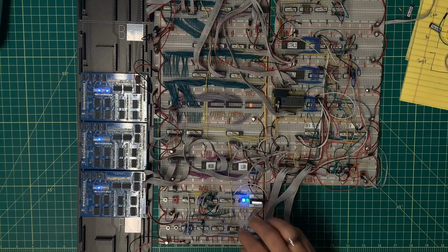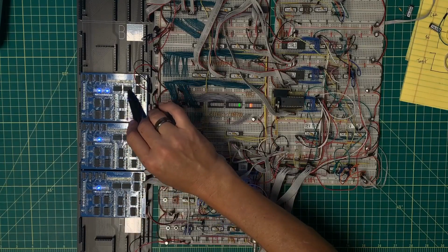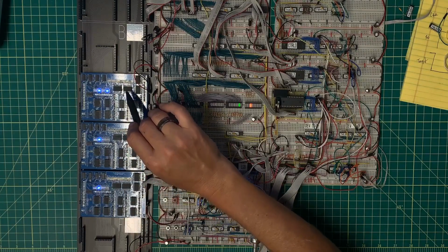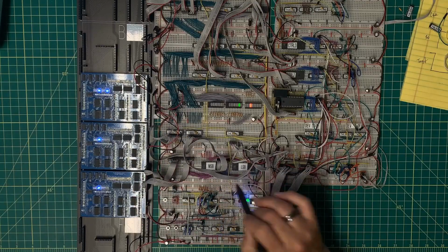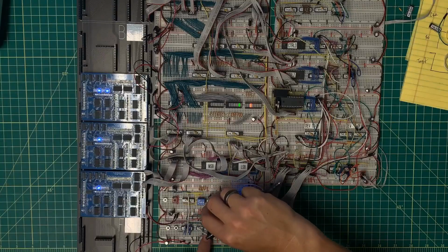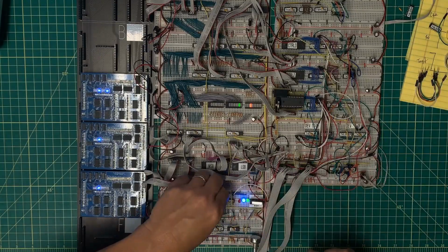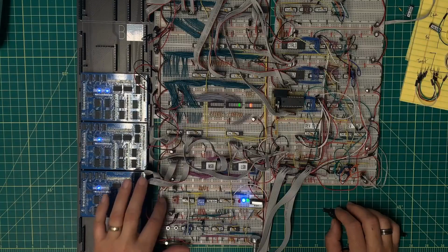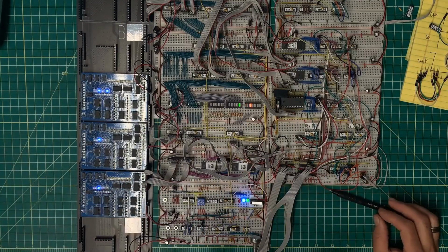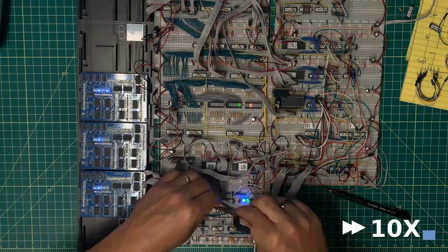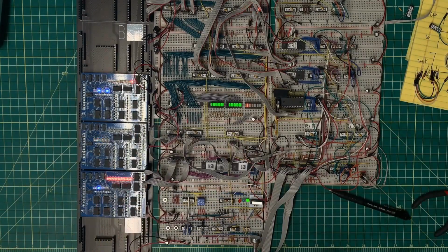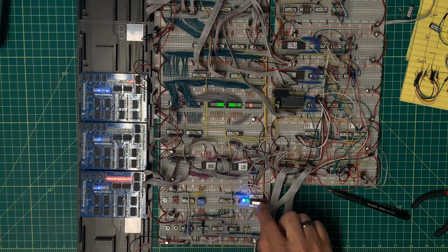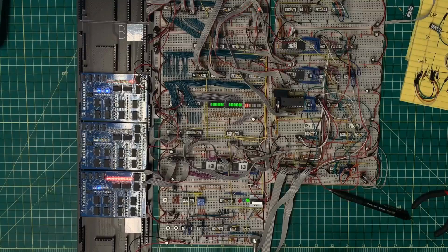And that's because the latch associated with the program counter has to actually latch properly ahead of the fetch here in the EEPROM memory. So this can go away now as well. Just do a reset to make sure. Yep. Let me see if I can get that 74LS04 out. Okay, so another reset, and that works just fine. Yep, that's working exactly like I need it to.